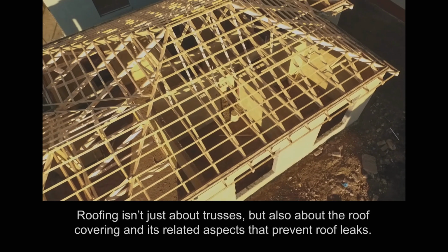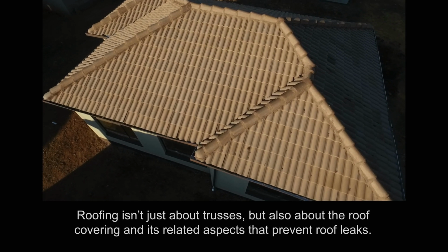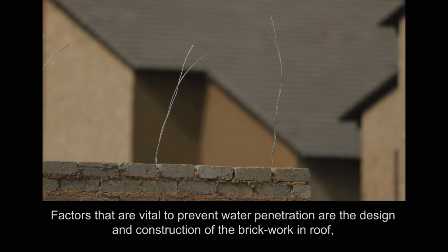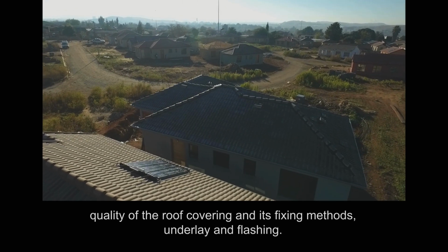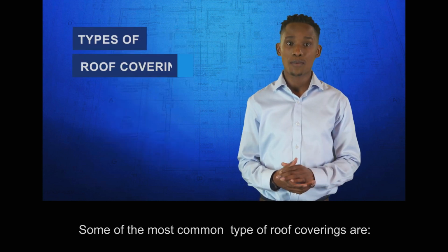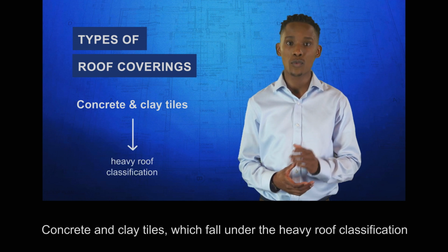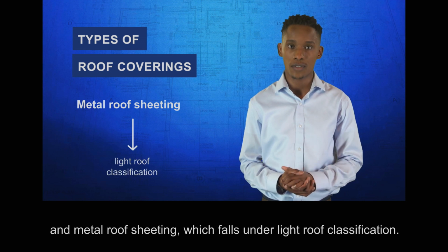Roofing isn't just about trusses, but also about the roof covering and its related aspects that prevent roof leaks. Factors that are vital to prevent water penetration are the design and construction of the brickwork in roof, quality of the roof covering and its fixing methods, underlay and flashing. These requirements are covered in SANS 10400 Part L. Some of the most common types of roof coverings are concrete and clay tiles, which fall under the heavy roof classification, and metal roof sheeting, which falls under light roof classification.